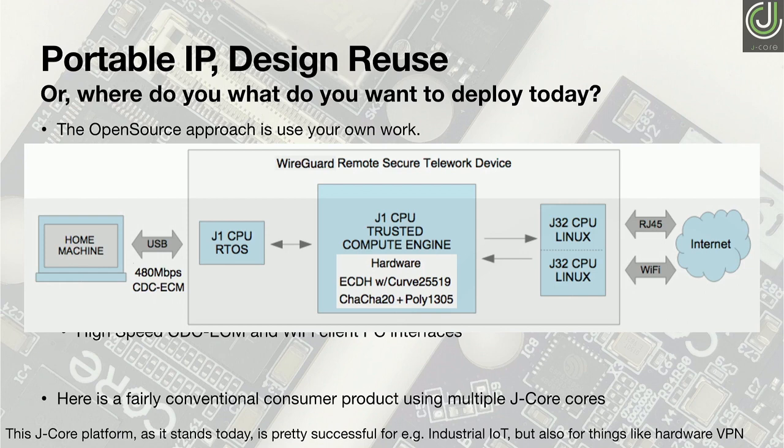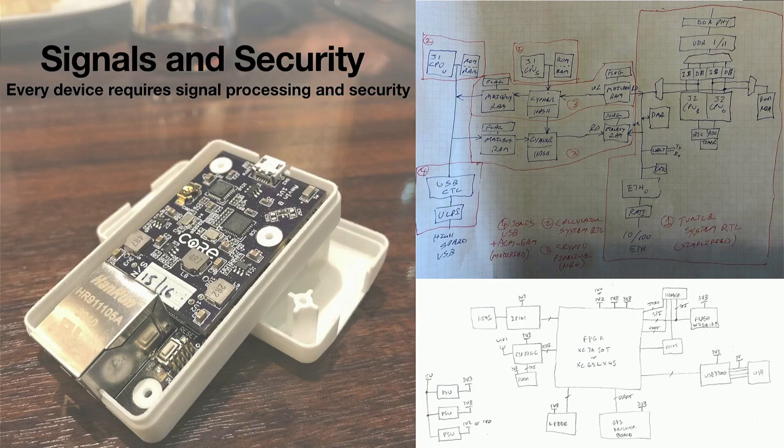And I brought them with me so if you want to see. So this is what the end device looks like. On the bottom is the CPU card, and on the top is the analog interface. And it really just starts with the concept. You know, what is it I want to build? And you start drawing out what the RTL flows would look like in order to put something like that together. On that side, you've got the Linux system. In the middle, you've got the cryptography, and on this side, you've got the USB controllers. And then the FPGA in the middle connecting to various different things. It turns out that the hardware itself is pretty simple.